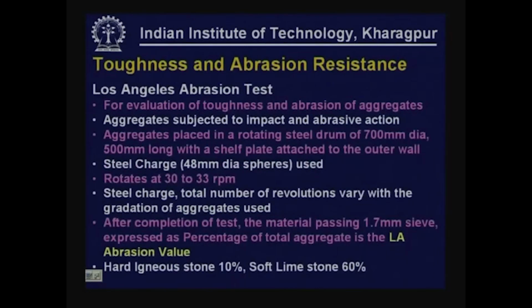The toughness and abrasion resistance can be measured using a popular test known as the Los Angeles abrasion test, which is used for evaluation of toughness and abrasion of aggregates. In this, the aggregates are subjected to impact and abrasive action.